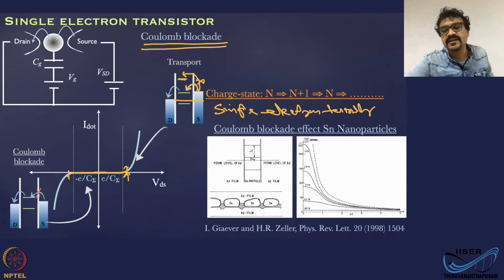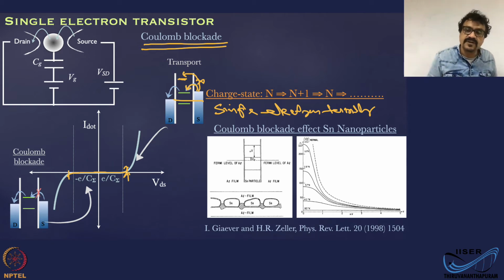Okay, and what you are seeing here is also an effect of temperature, which we will discuss later. The effect of temperature is to smoothen this curve. As you increase temperature, this curve will get smoother and smoother because the thermal energy also will contribute to this tunneling, so that the sharp turn-on of this curve will get smoothened by thermal effects.